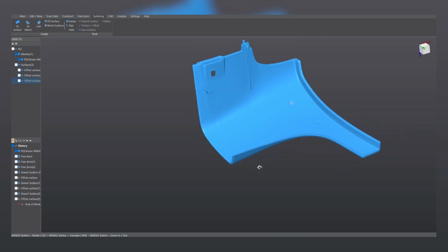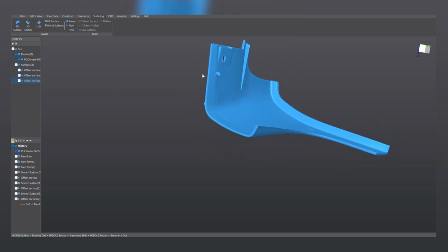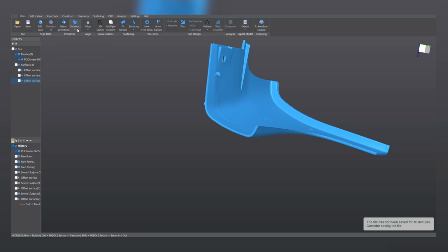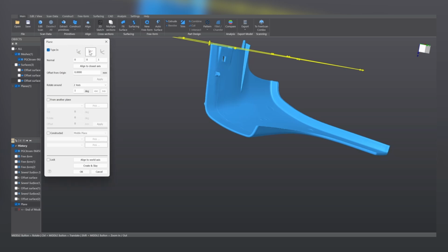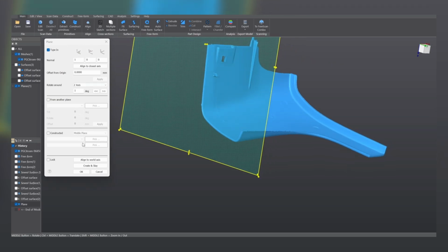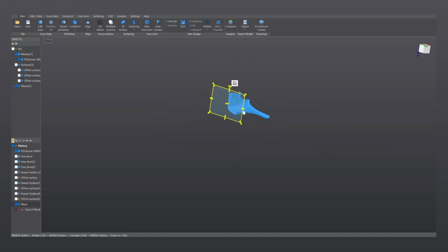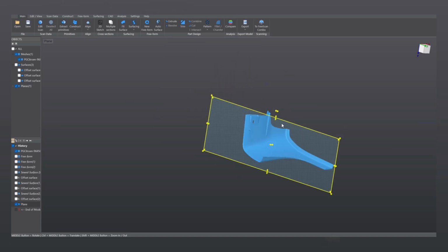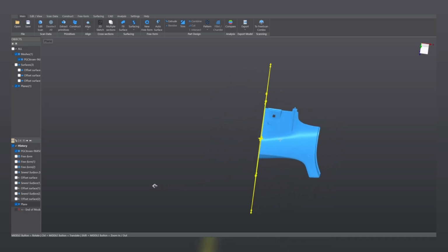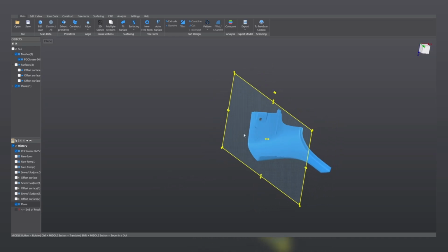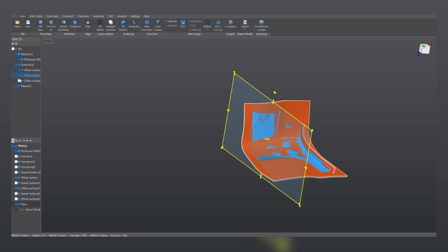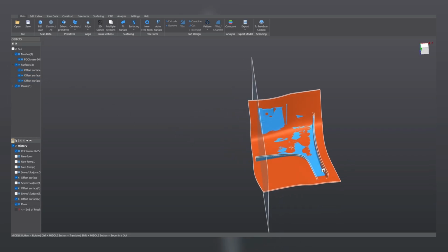Let's hide all of them first. And first thing I realize is that I need to trim them here on this side, which actually corresponds to the first plane that we used to align the mesh to the coordinate system. So instead of extracting a plane, let's simply construct it. We select the plane, this orientation at offset 0, meaning on the origin, and let's adjust its size a little bit, right? We have our nice plane here cutting actually my surfaces. Nice.